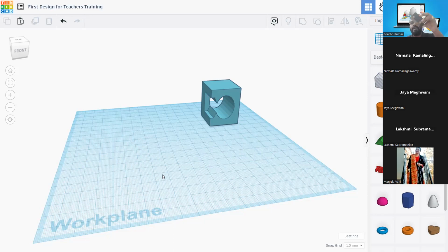First of all, I idealized different components and took the dimensions of different components like the motors and ultrasonic sensors. Then I designed the casing for those components and accommodated everything, which gave me the proper result of how this object will look after printing it using the 3D printing system itself.